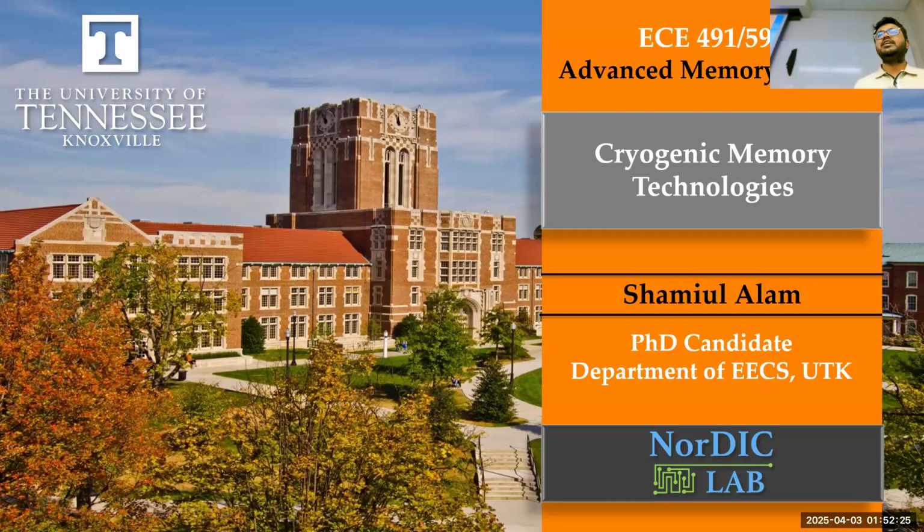So in today's class, we'll learn about these cryogenic memory technologies. I think you have already learned about different memory technologies like SRAM, DRAM, and flash, right? And in next classes, you will also learn about different emerging memory technologies as well. But unlike those technologies, cryogenic memory is not a specific technology, like SRAM is one technology, right? Cryogenic memory is not one technology, but you can consider it as an umbrella of different technologies that can operate at a specific environment, right? That environment is cryogenic, which is extremely low temperature.